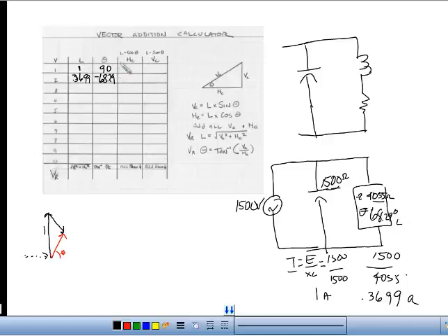So how do you find the horizontal and vertical components? If you just think about a capacitive vector, it's purely up and down. It's zero horizontal. It's purely vertical. You can test it: the length of the vector times the cosine of the angle will give you the horizontal. 1 times cosine 90 equals 0. 1 times sine theta, or 90, equals 1. Right? Why is that? Well, you could go back and review your trigonometry for that.